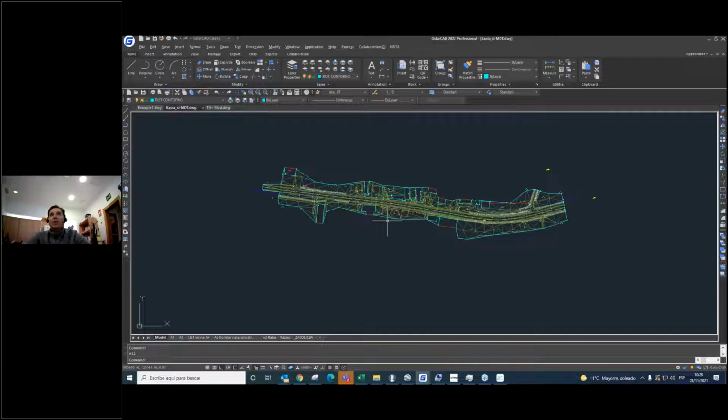For example, I'm going to create contour lines. In this case, we can have a look and evaluate the elevation of this work and use the interval to name the surface. We can use a palette color to represent the contour lines, etc. Okay, and here is our surface.